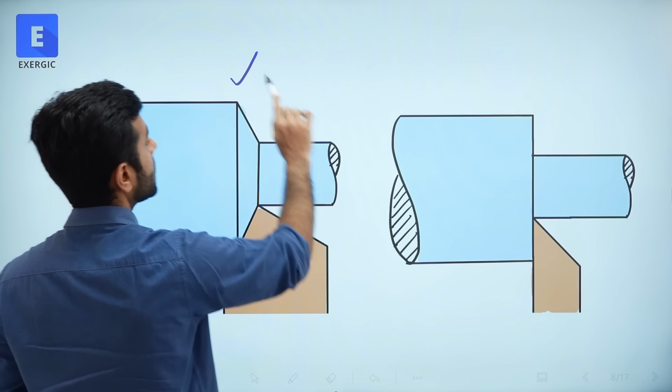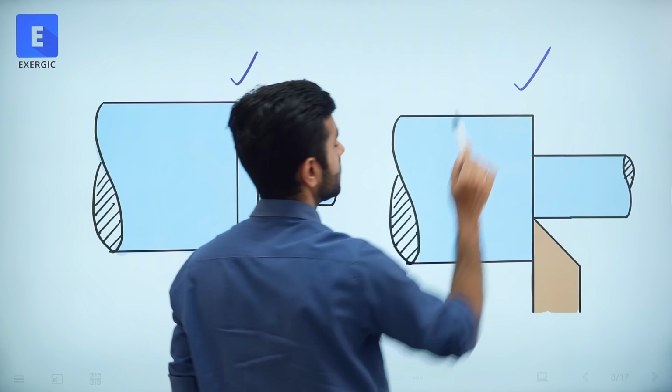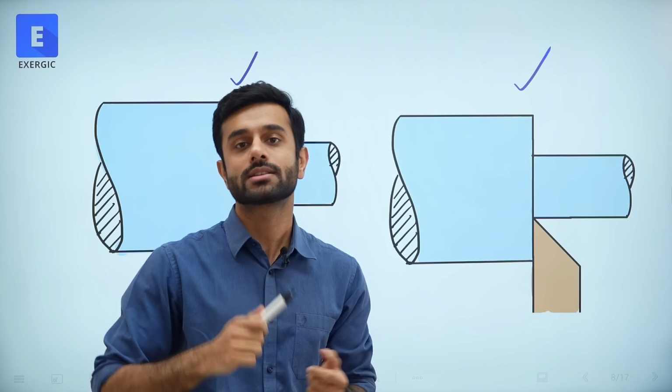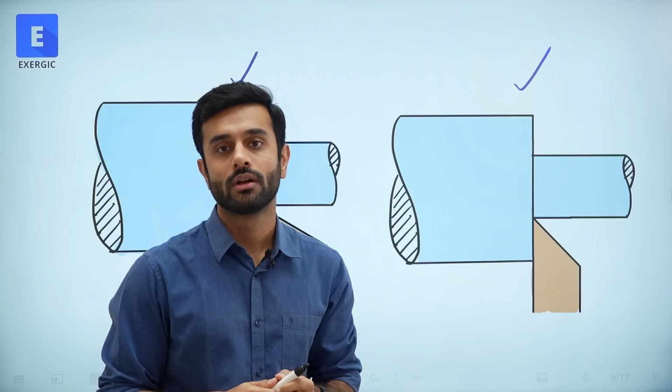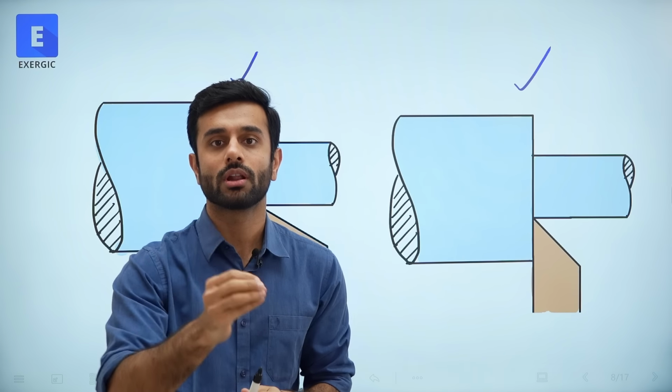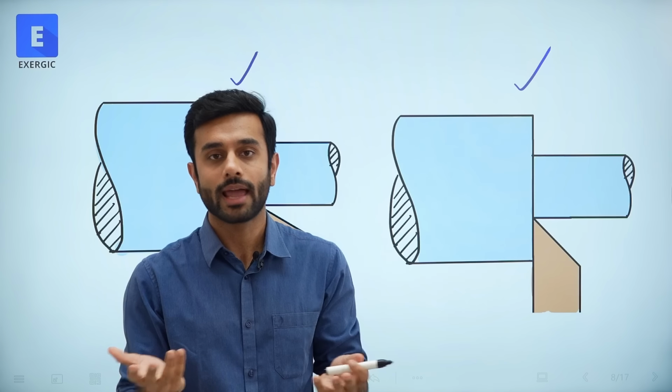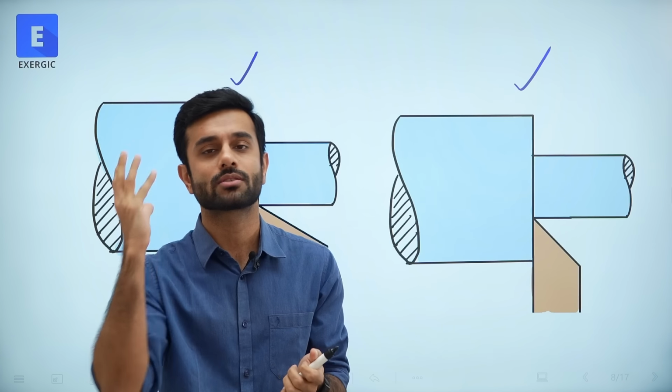They will say this is oblique cutting, this is oblique turning, this is orthogonal turning. Arey? Inclination angle decides whether it is orthogonal or not. Who told you that orthogonal or oblique will be decided by side cutting edge angle? That's absolutely wrong concept. Find me this concept.